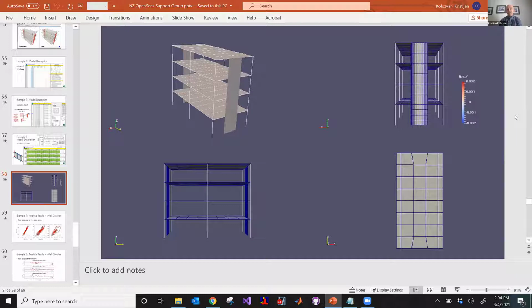That was just based on the test and the confinement that we had. And the shear stiffness is, I believe, standard, like half of G, 0.5 G for cracked shear. It was just the linear elastic shear. So we didn't do that much. One parameter we definitely played with was the stiffness of the slab to observe that sensitivity. But other than that, not really.